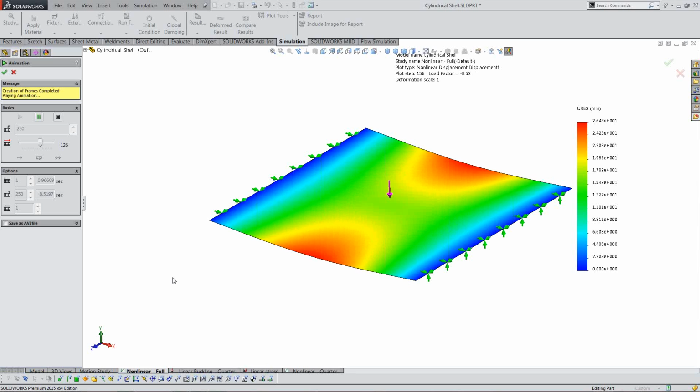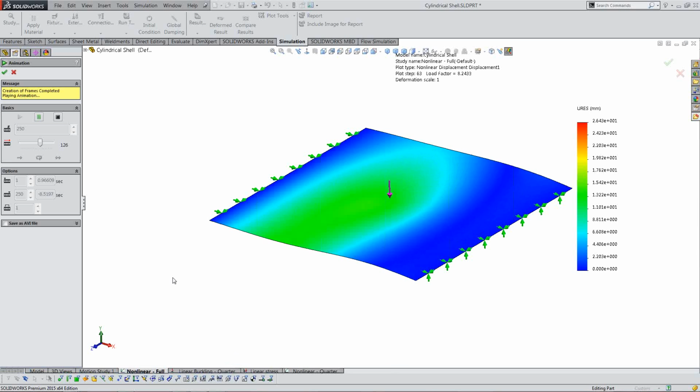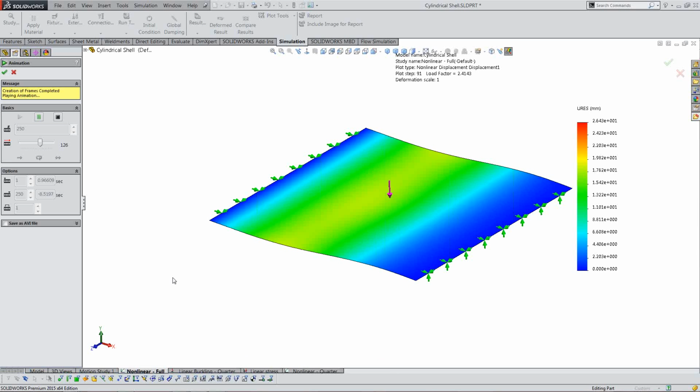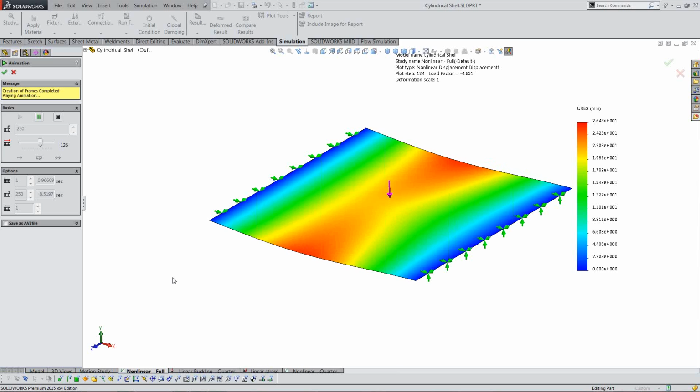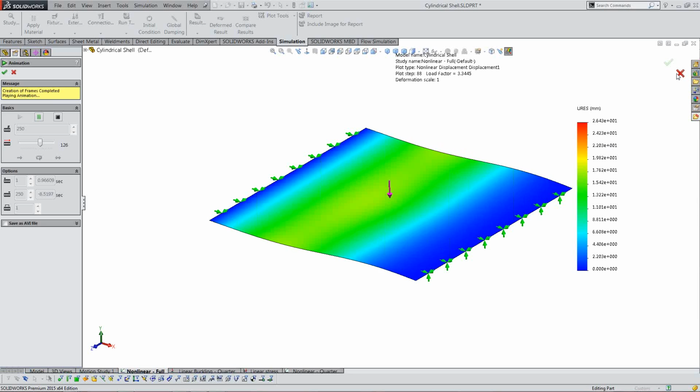So this type of buckling behavior cannot be captured in a linear study accurately. So yes, the linear study is useful, but it simply predicts the eigenvalues in a manner similar to a frequency analysis based on a constant stiffness in the structure, and gives you a result. And you have to take that result with a grain of salt, and understand that it's conservative, whereas a nonlinear study has much more capability to be able to track the behavior.